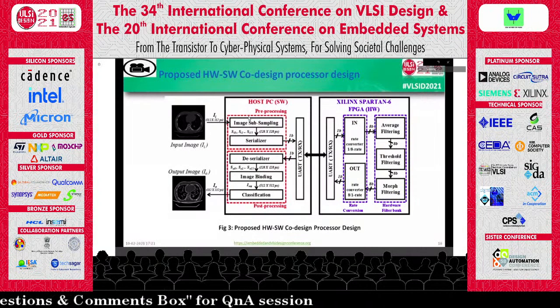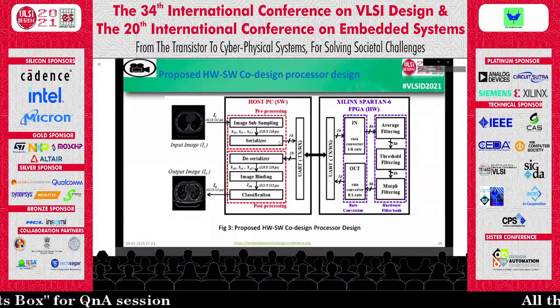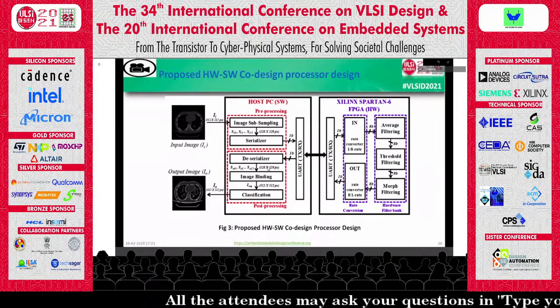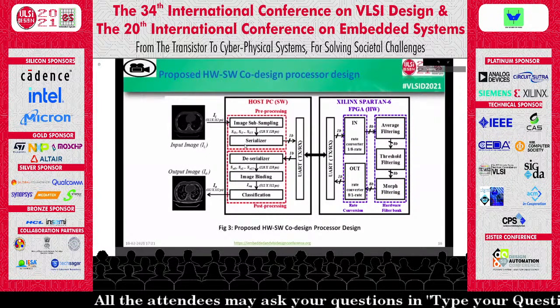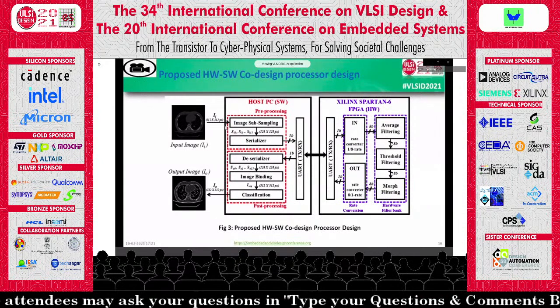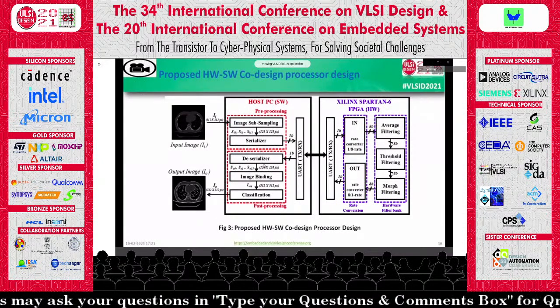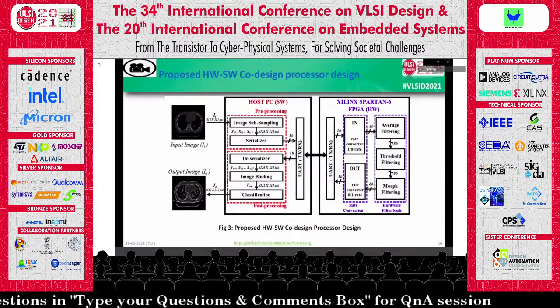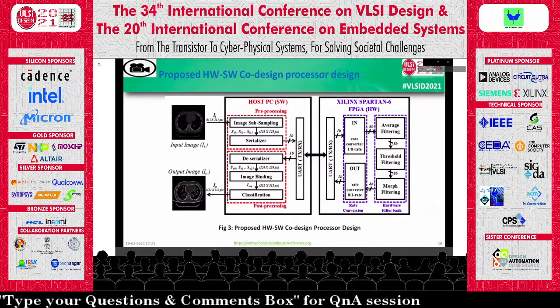The hardware-software implementation of the defined image processing algorithm majorly consists of pre-processing, detection filter, and post-processing. The pre-processing block performs image sampling, padding, and serialization. The image sampling block divides bigger images, that is 512 by 512 pixels, into smaller sample images, 64 by 64 or 128 by 128.